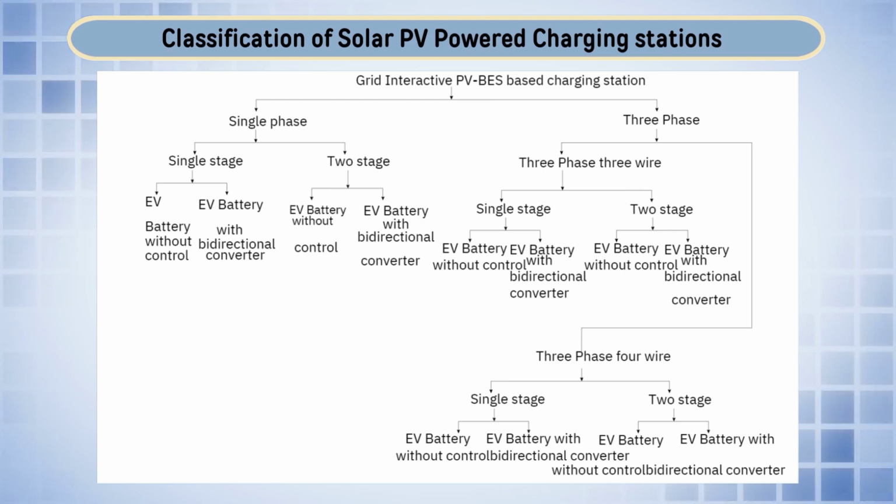The same converter which is utilized for DC to AC conversion during renewable integration performs the function of MPPT as well as converting the power from DC to AC to fulfill the EV demand, where at the point of common coupling various onboard and offboard chargers are connected.